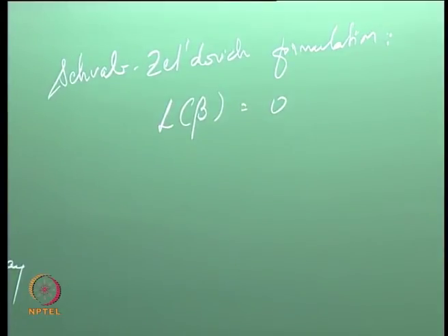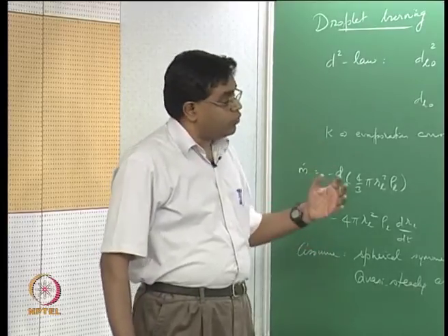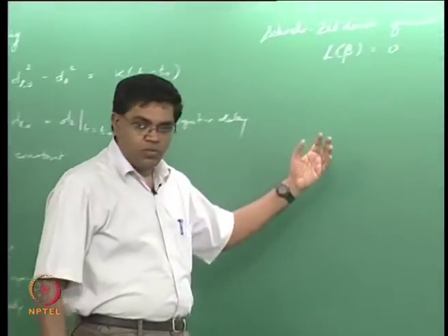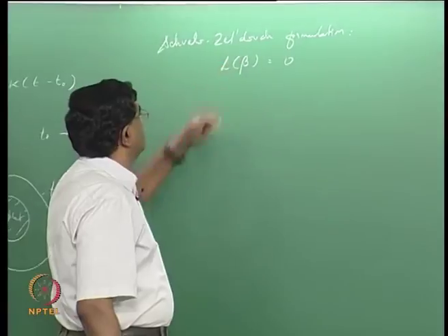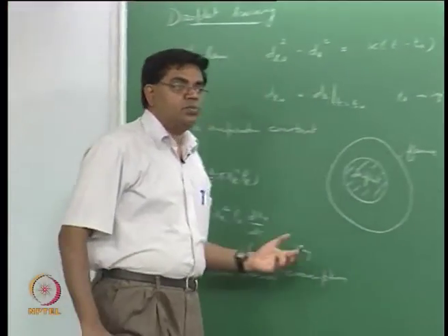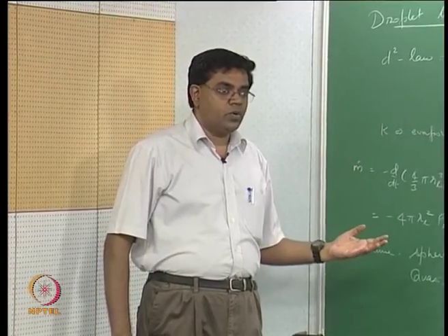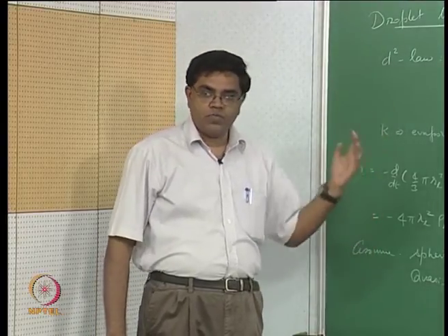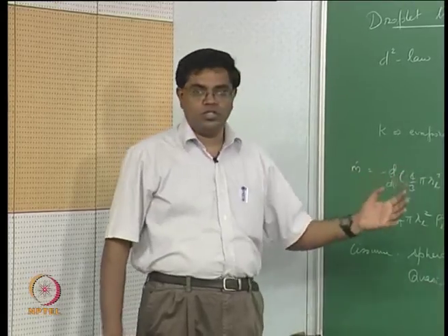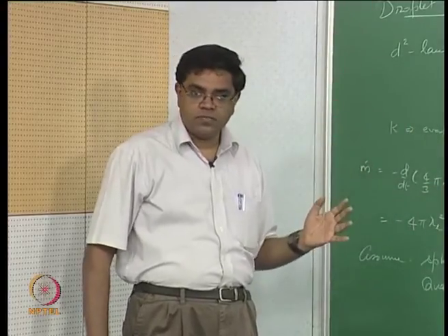For n species we have n betas and 1 alpha, so n plus 1 equations. But as we did earlier with the premix flame and the Burke-Schumann diffusion flame, we now choose those particular alphas and betas that are most pertinent to what we are doing, so we don't necessarily have to worry about n plus 1 equations.